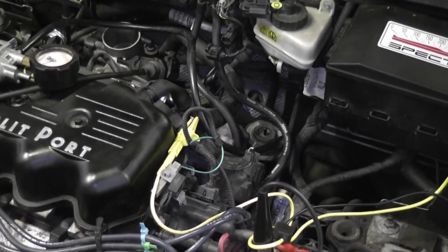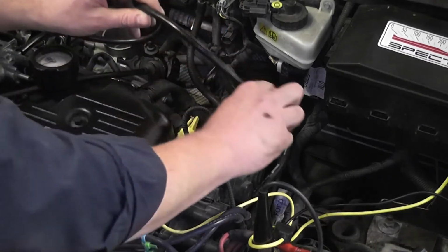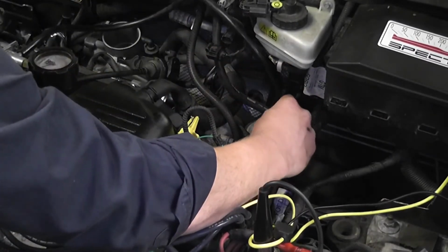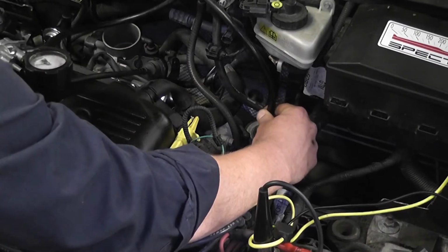Alright, so we started the car. I know what some of you are probably thinking. This is a mass airflow engine. We're running it with the mass airflow unplugged. That's okay. Ford has good backup strategy, so you hear the car's not running too bad with that out of the picture. Checking the EGR, I'm just going to pull a hand vacuum pump on the valve, and we're going to listen for the RPM to get real rough. We want it to just about stall the engine out.